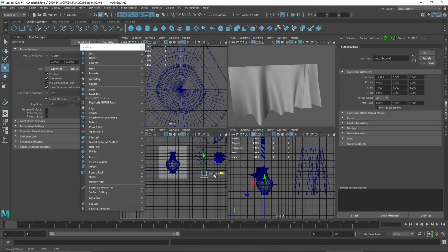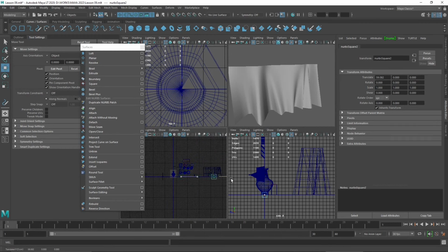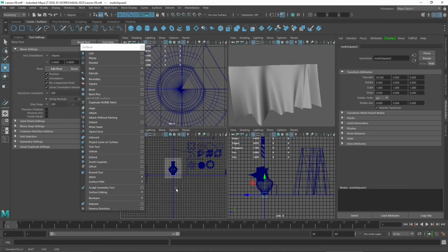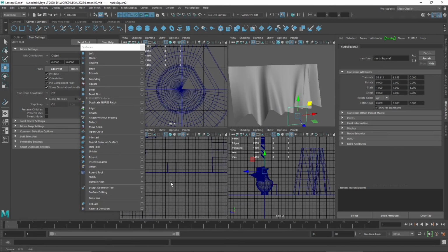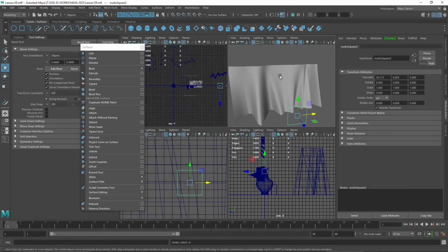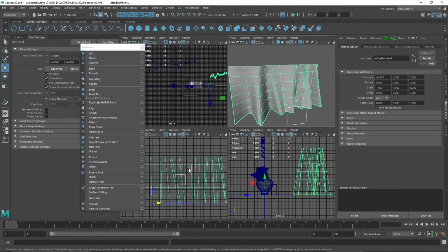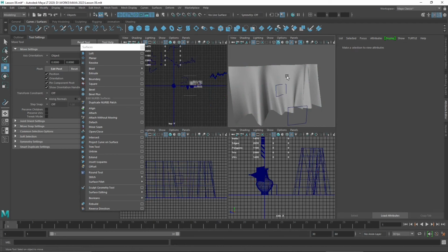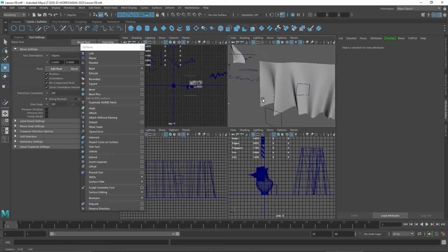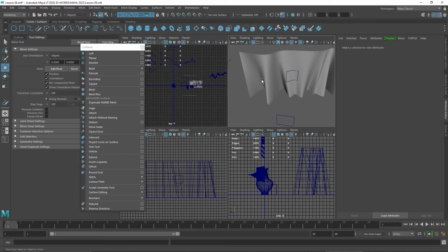Okay, so you can see there now it's oriented frontally, and I can move it in the front here. There you go. I'm gonna move it so that it's in front of my curtain, and that's the object where I want to project. So first select the square, then select the surface, and then go to project curve on surface. You can directly click there, or go up on the toolbar and click, and that's it. So that's your 2D curve projected onto the 3D surface.